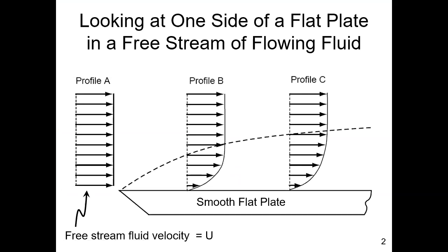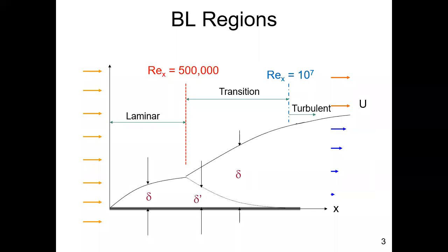We were talking about flat plates and that this boundary layer is created by the difference in velocity between the surface and the fluid. And that difference is initiated by what we call the no-slip condition. The fluid at the surface has the velocity of the surface. And this boundary layer had different characteristics, whether it was moving in structured organized flow in fluid laminae, known as laminar flow, or if it was characterized by mass vortices, or what we call turbulent.